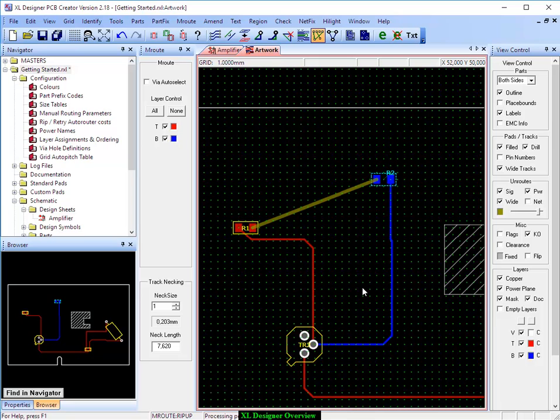And so if you were manually routing a design, you just have all your interconnections like that, and you use the MRoute corner command, or this icon here, and it's a right click to insert a track segment. When it comes out of surface mount components, it'll only allow you to come out on the layer that the component is on.